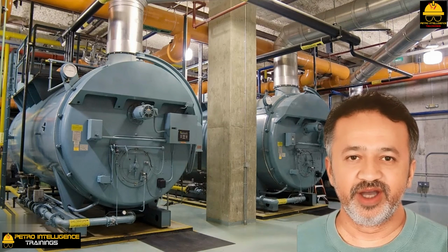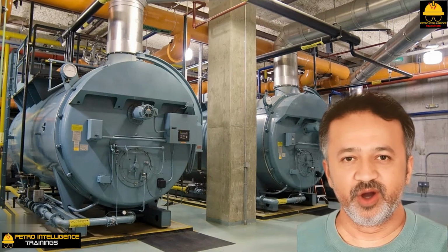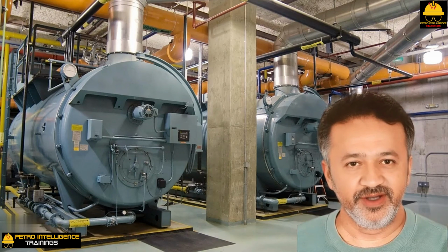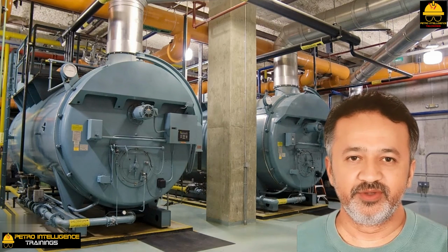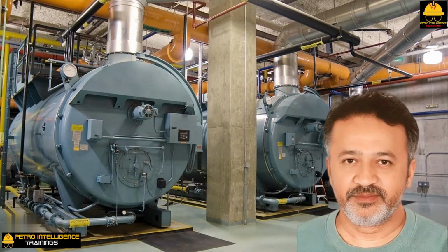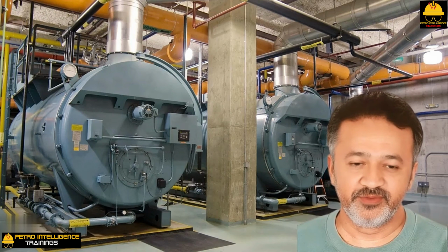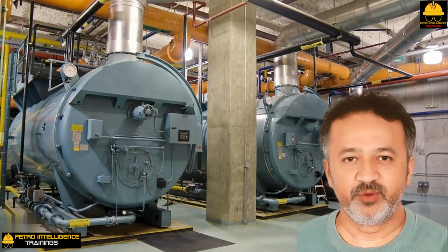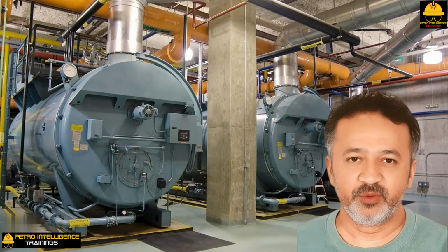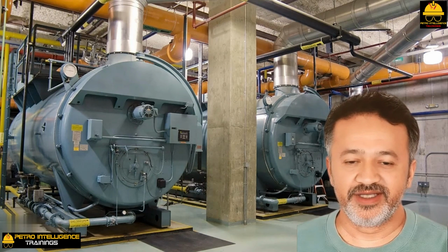If the boiler is firing high sulfur fuel oil, 2 to 4% sulfur, this may be a problem. The dew point of H2SO4 in the flue gas may easily be as high as 450 degrees Fahrenheit. The 230 degrees Fahrenheit water inlet may cause the flue gas temperature to drop below 450 degrees Fahrenheit. This will precipitate a weak H2SO4 mist, which will aggressively corrode the fins or studs of the economizer tube bank.